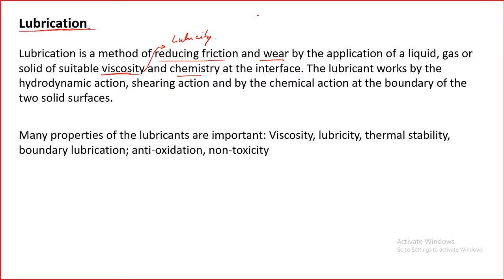So we need to have lubrication because for many machine elements the load and speed or velocity are all decided by the design parameters. We don't have much control. Even the environment we don't have much control over, because these are decided by the design requirements, and accordingly the material will be selected. So the tribological system, where the contacts will take place, sliding or rolling, basically sliding, is subjected to all these kinds of loads, velocity and environment. We don't have much control. We should also add temperature, thermal. So we have to study the tribological system very carefully and provide a proper solution.